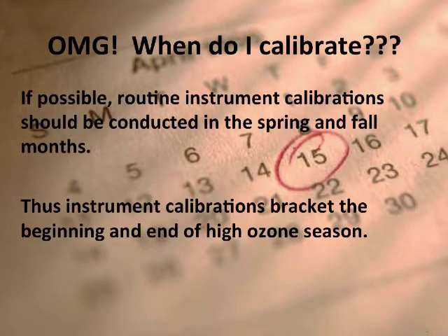And I realize this is not always possible, but if you can, it's always helpful to bracket your calibrations in the spring and the fall, so they bracket high ozone season, the beginning and end.